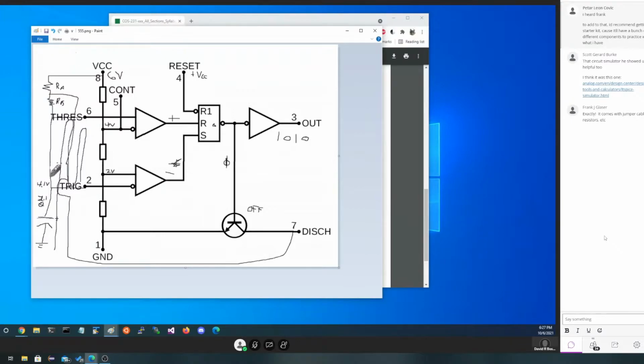When we discharge, we're only discharging through one of them, through B. So charging will take longer than discharging because charging takes 2 resistors, discharging takes 1 resistor to pass the current. And we know that you're going to have more resistance in the circuit because obviously this resistor doesn't change values when we're charging. So we expect the on time to always be slightly longer than the off time.